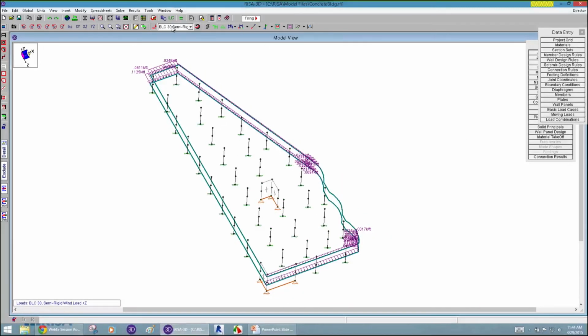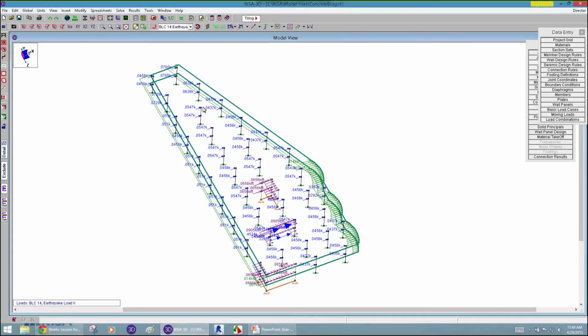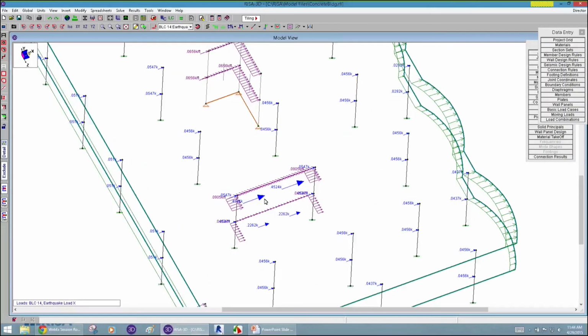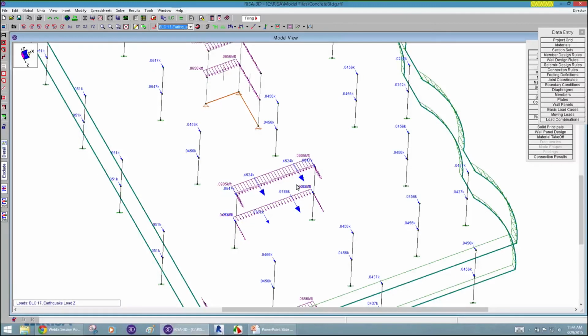And we also have that earthquake load. So if we jump back to the ELX, now that earthquake load, we saw it lumped in per each column. We see there's a surface load that's being applied. We also can zoom in a bit, and we see that now whenever we had that equipment load, that dynamic mass, it also turned that value directly into a lateral load in the X or the Z direction. So that's pretty simple here. Just automatically does that for you.